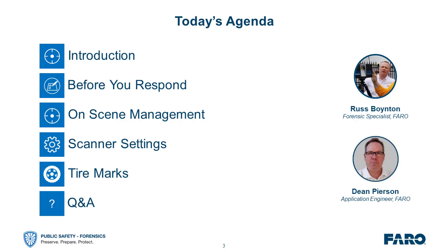So I'm going to show you how to do those 2 today using a point cloud that's been imported from FARO Scene software into FARO Zone 3D Advanced software to show you how that process is done. And the other 3 ways are video analysis, crush analysis, crash data retrieval, of course, and then momentum analysis. And those we will not get into today, we just don't have the time to do that.